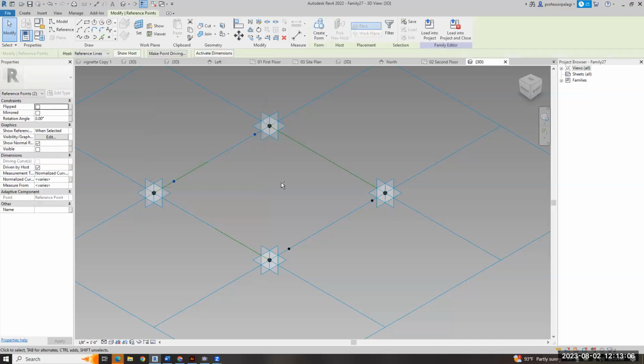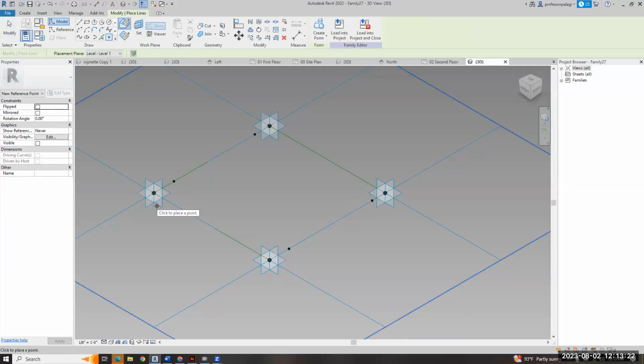Now I want those two and these two, fancy selection, to be a set distance. Now, what's the set distance off? I want the 8 inches over of the gap plus half of that, which is 4. So 4 and 8 is 12. 1 foot off will be the center line of those beams. Okay.